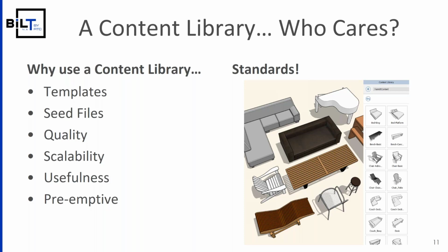That's key because that's where the material transfer technique works. It only works with Revit 2018, and it only works with that newer version of the add-in. So do a double check on your system and make sure you don't have 1.9.3 installed, because you will miss out on that. Yeah, and the material conversion only works with Revit 2018, not Revit 2017.